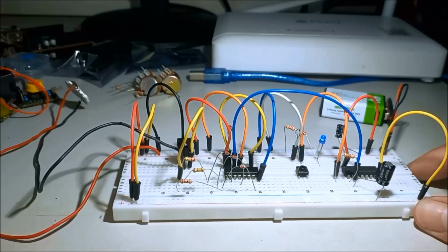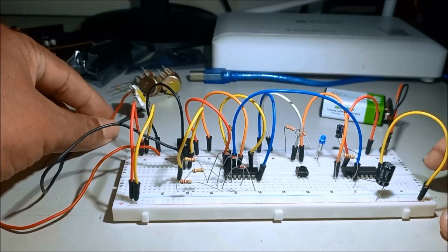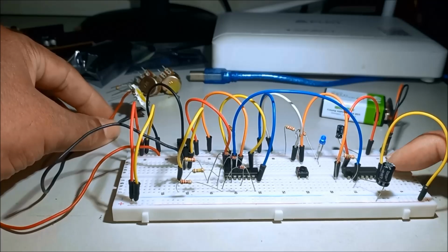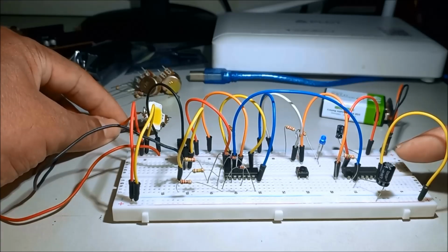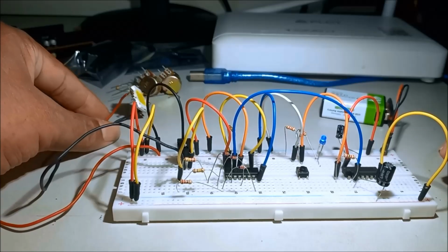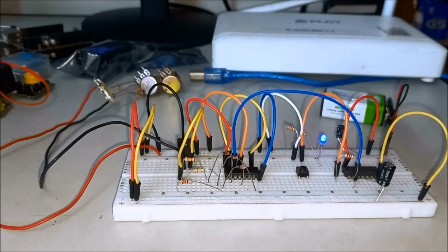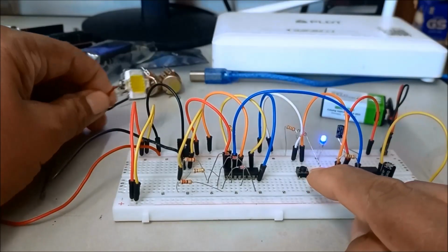Let us now see the improvement of our circuit. I added the switch debouncing IC 7414. In order to eliminate switch bouncing, this is a debouncing IC. Let us again test. When I press the switch,